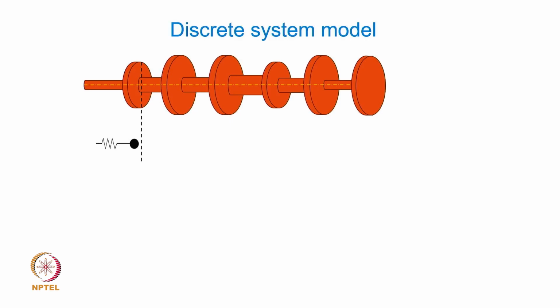and the remaining part is the stiffness element. Now, if this is to be treated like a torsional vibratory system, like the gearbox which we saw, the more dominant vibration is going to be torsional vibration, going by the torque transmission that happens in it. So if this segment represents this inertia and this spring, the spring is essentially representing the torsional stiffness of the shaft, which is going to resist the twist in the shaft.